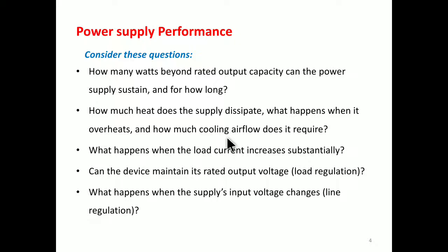Third one, what happens when the load current increases substantially? If you are taking one load condition, what happens if the load current increases substantially? That is very important. Next we can go for the line regulation and the load regulation. That is, can the device maintain its rated output voltage? That is for load regulation. Next one, what happens when the supply input voltage changes? That is for line regulation. So for the testing of performance, we have to raise and answer these questions. That is very important while checking the performance of the power supply.